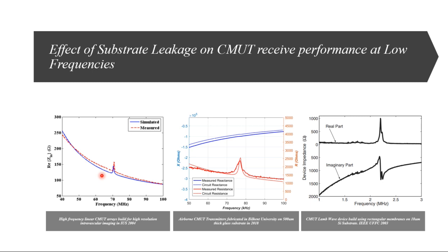But you can see that the CMUTs, which have vibrating membranes, because you can see the frequencies being swept by applying a certain peak amplitude signal from an impedance analyzer. And once you do that, the membrane starts vibrating, and given the structural, geometrical, and material properties, you observe a resonance. Okay, that is particular to that geometry.